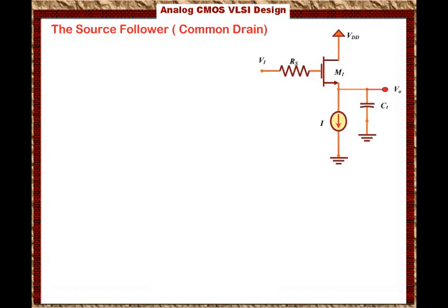Usually this capacitance is set by the standard or the manufacturing process. For example, if the output is connected to an I/O pin, then depending on the technology, CL will be specified to be less than some maximum value. You have to meet the specification for CL.